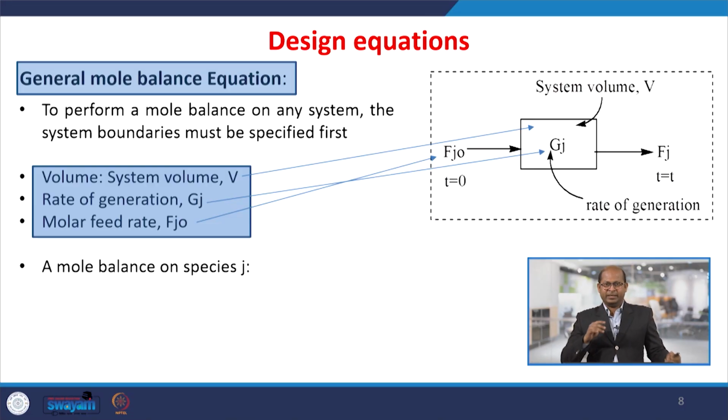So, at the beginning we will develop a general mole balance equation, and then by choosing a particular reactor we develop the design equation for that reactor. That may be batch reactors, plug flow reactors, continuous stirred tank reactors, packed bed reactors, or other reactors, with design equations depending upon that choice of reactor. We can implement that design equation to find the volume of the reactor or the catalyst quantity required. Or we can compare the volume of one reactor to another.